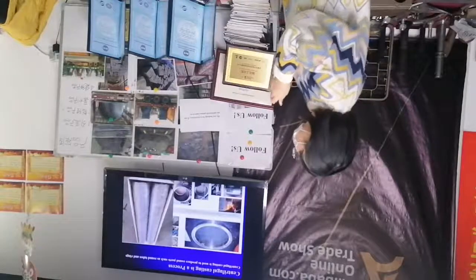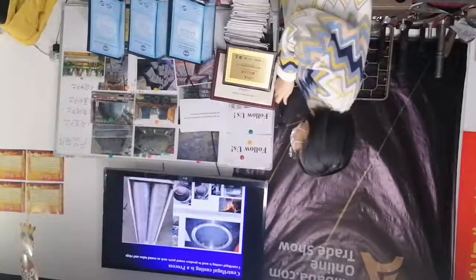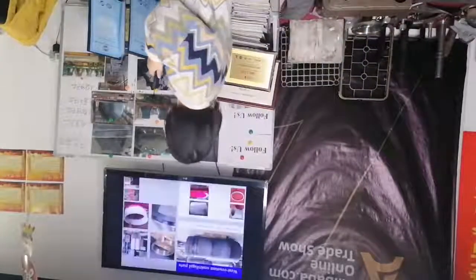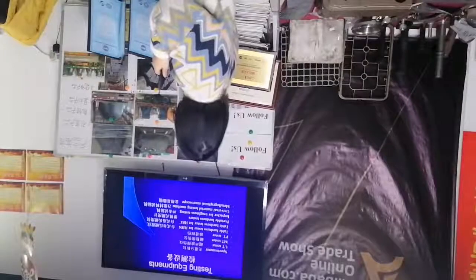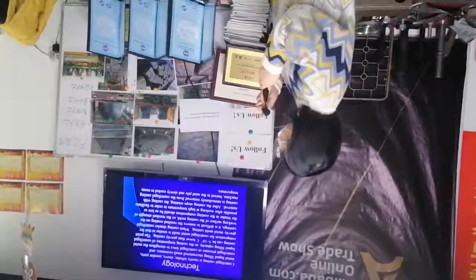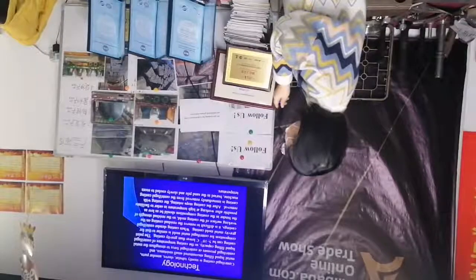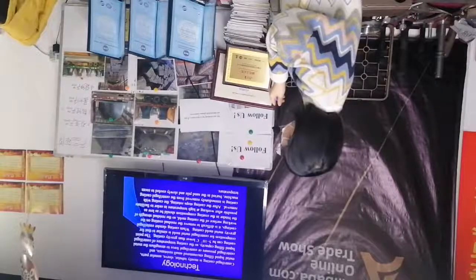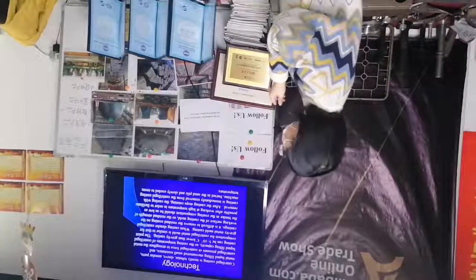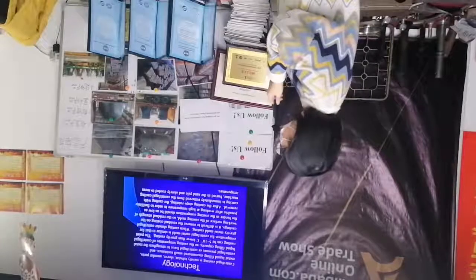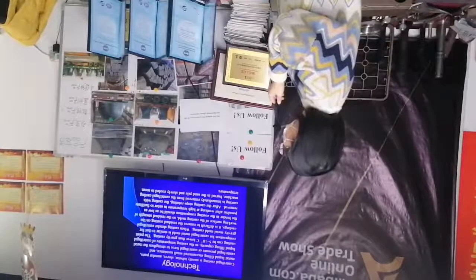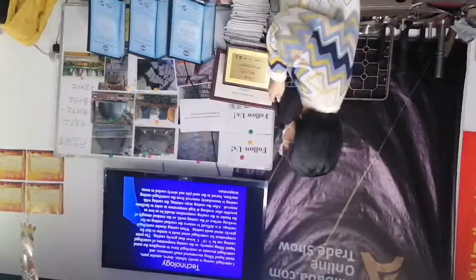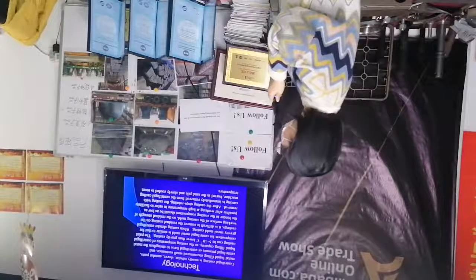Centrifugal casting is used to produce round parts such as round tubes and rolls. In the technology of centrifugal casting, the metal encounters small resistance during filling. After the casting stops rotating, the casting is removed from the centrifugal casting machine, buried in a sand pile, and slowly cooled down to room temperature.